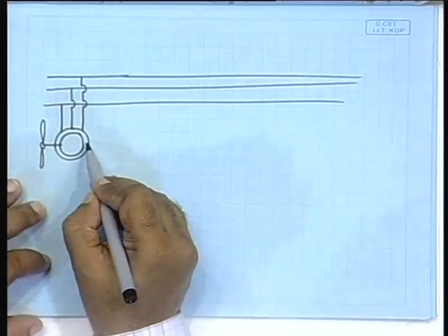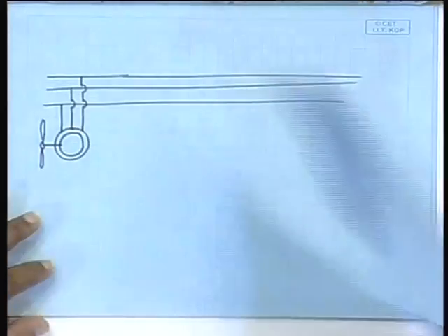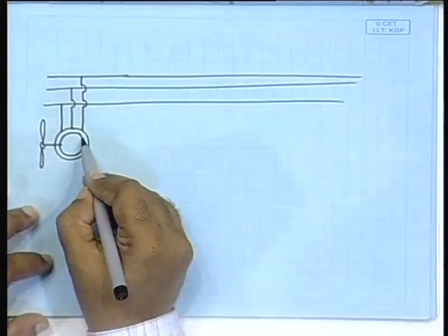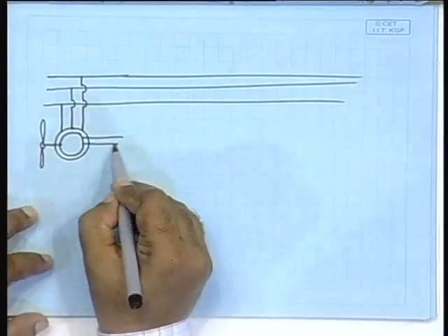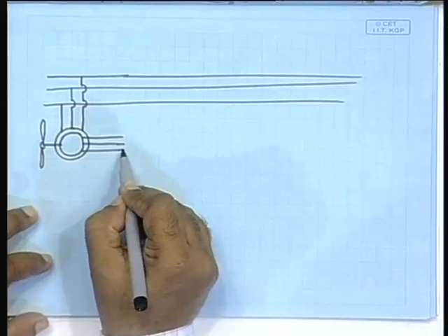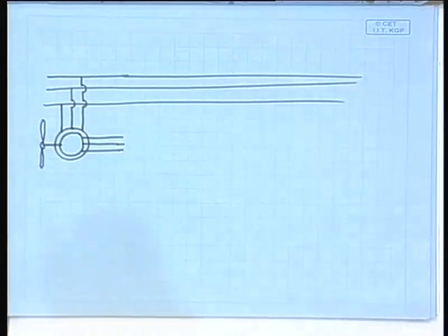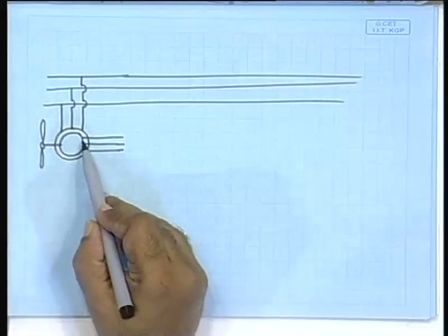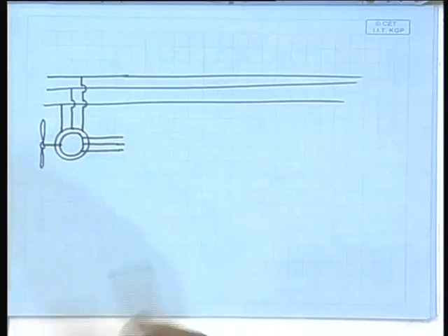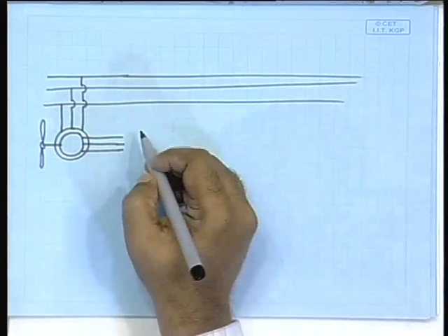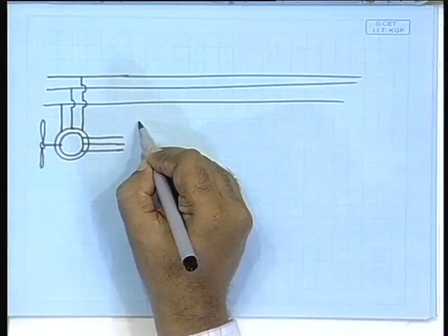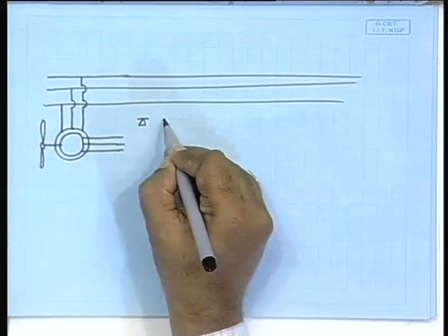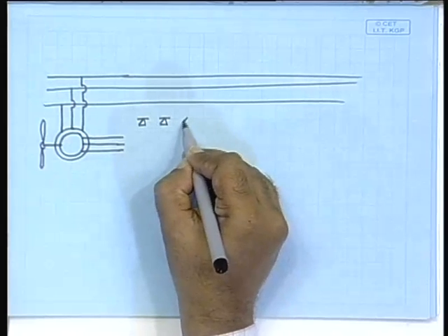So, here you have, how do I draw? In an arrangement something like this, through an arrangement something like this, you have the rotor terminals available to you. So, you have the stator terminal connected directly to the grid, but the rotor terminals are available to you. So, what do you do with them? Here firstly we convert them into a DC.